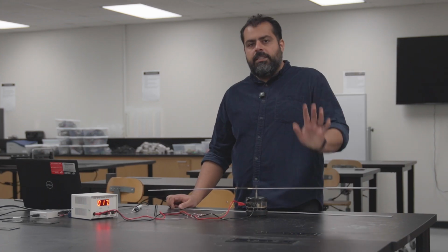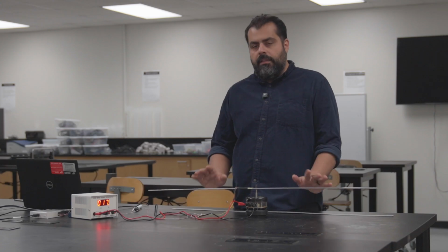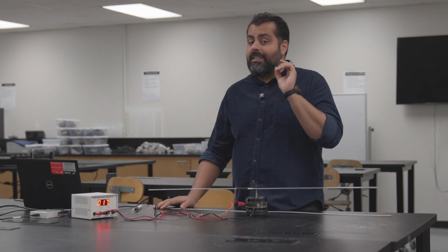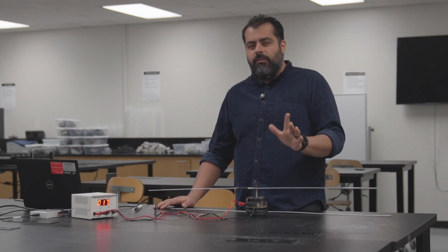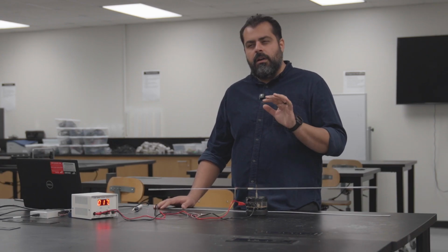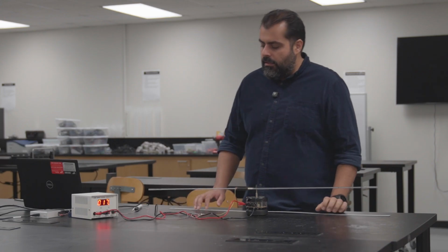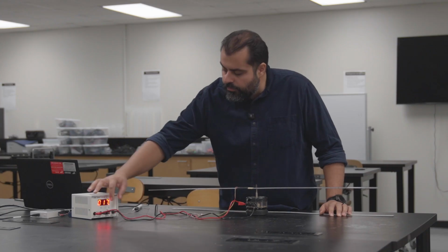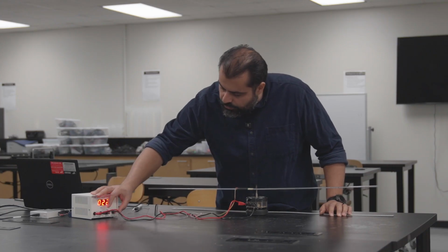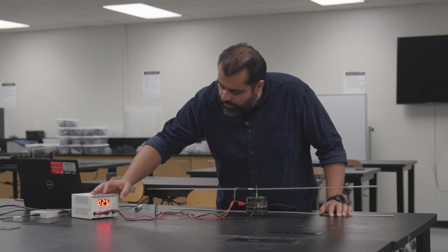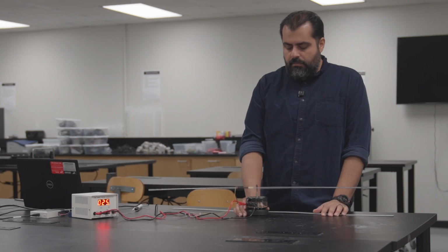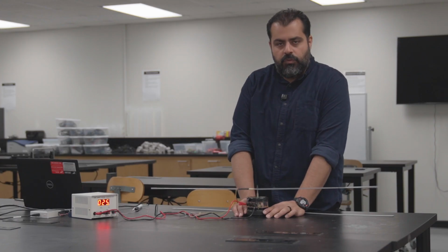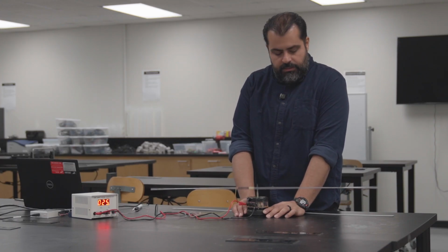Okay, so we have the first mode of vibration for the free beam. We have done the measurements. We are going to move to the second mode of vibration for the cantilever beam now. I think the natural frequency should be around 23 hertz. I might be wrong for the values, but as long as you are in the correct range, you should be fine. So let me move this on to 25 to be sure. And at some point, because of how the shakers are made, this might actually start moving. You might want to hold on to this.